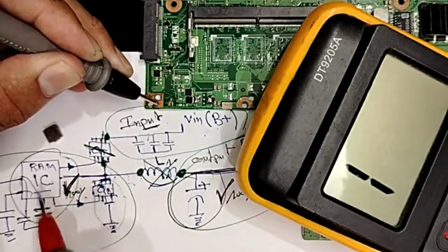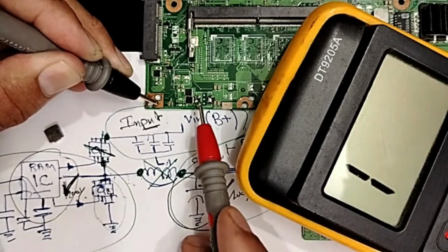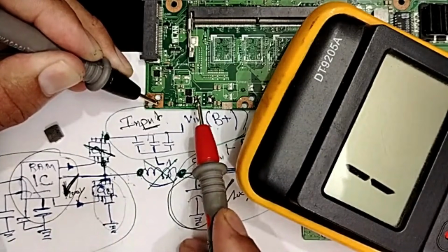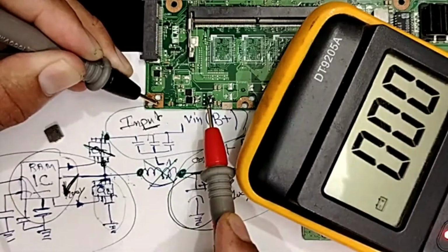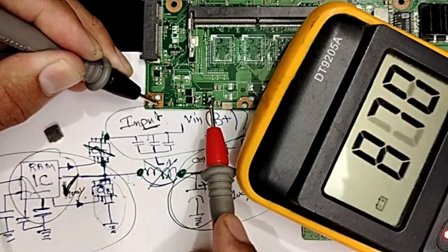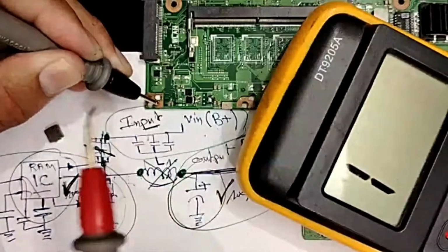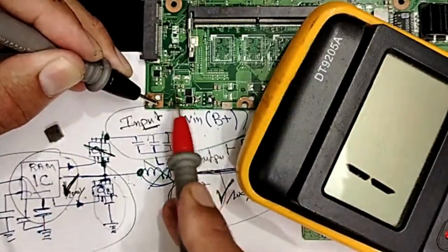Means the IC also is good. Awesome. Means the ceramic capacitors also are good. No short in this side. What about this side? We have a short. Finally, one component. Guys, I removed one component from the board and I located the short part without damaging the MOSFETs.